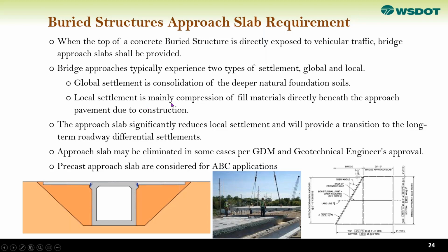And the local settlement is primarily compression of the fill materials directly beneath the upper pavement due to construction. The approach slab significantly reduces the local settlement and provides the transition to roadway differential settlement,